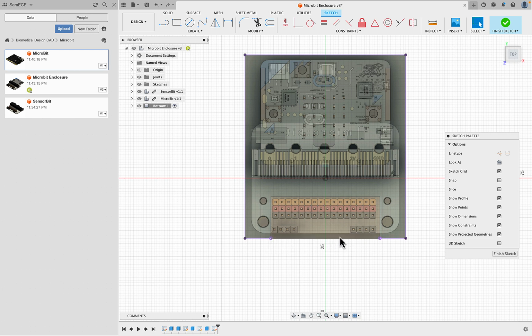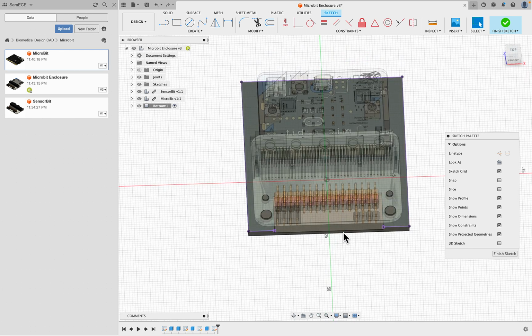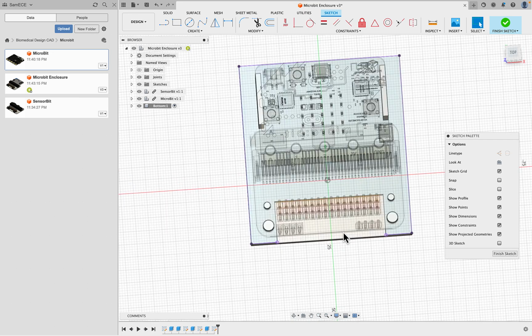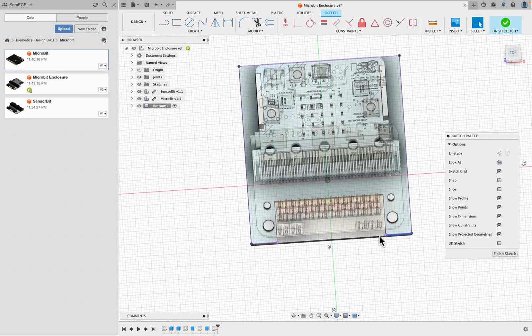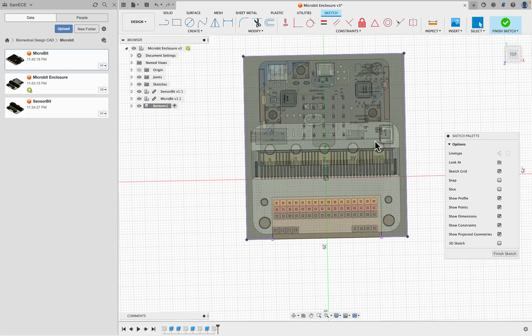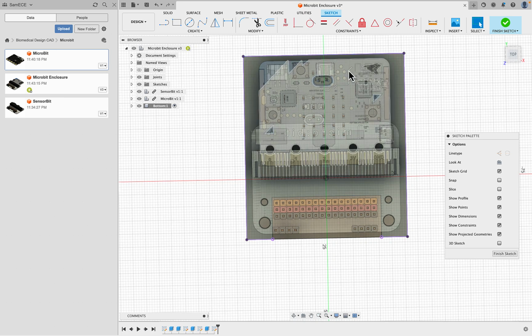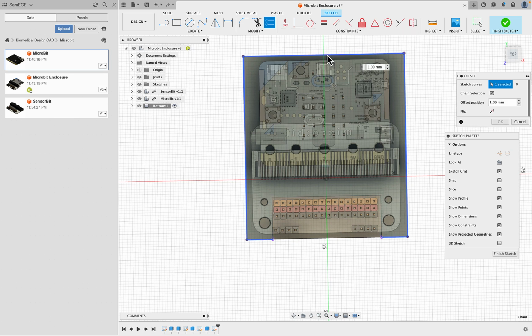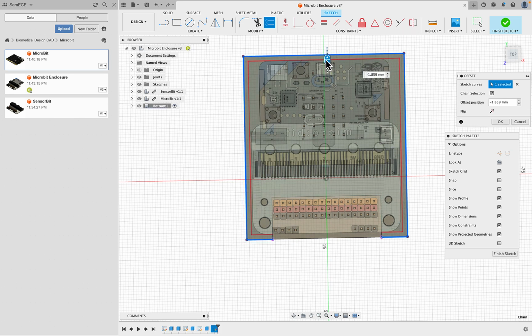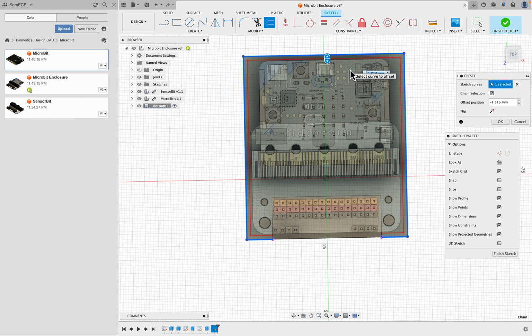This one is because we did the cutout for the various pins. Actually, all the way through we'll need to correct this, because there should be a wall, there shouldn't be a hole here. There's really no reason why this rectangle goes all the way to the edge, so I'll correct that in just a moment. So let's do another rectangle. We can actually just hit O for offset, and let's do a wall size of about 1.5.